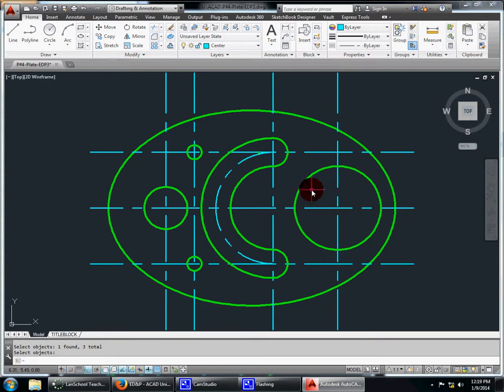Excellent. Now all we need to do is shorten the center points so that they look like the example and fit inside the object. So I'm using my node editor to do that. You could, let me show you. Technically, you could use your trim command, and you could come in here and trim parts of it like that to get rid of it. I mean, there's really no right or wrong on how you're doing it, as long as you're getting the work done.